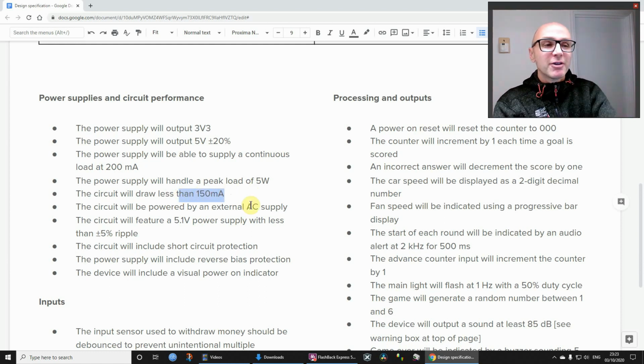And if you capped it, honestly, for the majority of student projects which involve microcontrollers and a few potential dividers and a few LEDs and buzzers and things like that, probably, yeah, 150 milliamps will be fine. If you configure your LEDs right, they're probably only pulling between about 5 and 10 milliamps per LED. Okay, trivial. Microcontroller pulls absolutely nothing, and buzzers as well, like 10 milliamps or something. So just add all of those together.